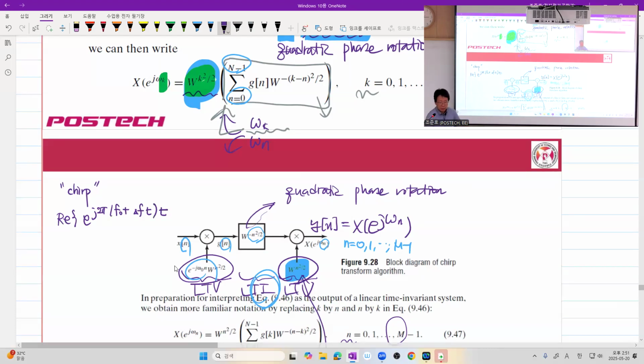something like this. And you may say that, hey, professor, you have a typo, actually it is not. This is plus. Some constant, alpha. So it's actually cosine of 2 pi f0 plus alpha t times t. And you may view this as the so-called instantaneous frequency.